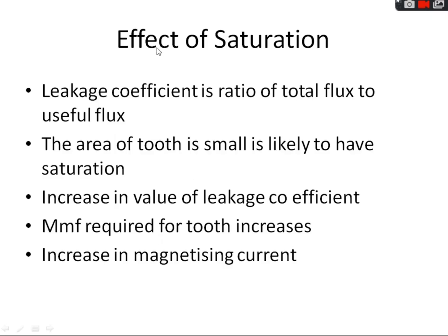So the effect of saturation is that it usually leads to an increase in the magnetizing current, and if the magnetizing current increases, the no load current will also increase, and the motor will draw very high current during starting even under no load condition. So saturation affects the starting performance of the three-phase induction motor, in the sense that the starting current drawn will be very high.